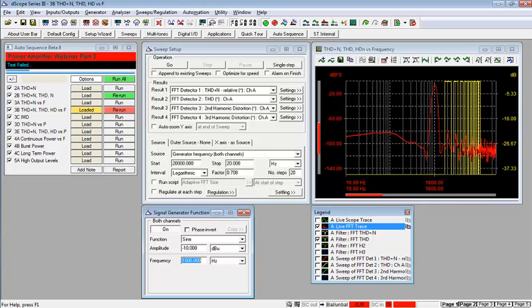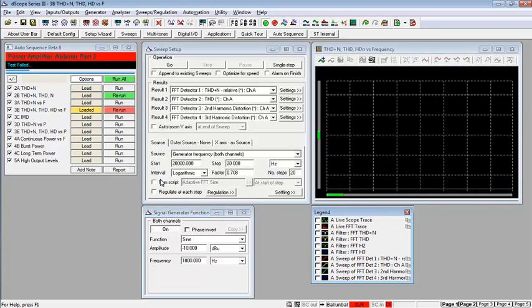What I want to do is to run a sweep that gives me the best of both worlds. I want to have a small FFT size at high frequency where I don't need the resolution but I would like the speed, but I want to use a large FFT size at low frequency where I have to in order to obtain the required resolution. So what I'm going to do is turn on this clever little script here, adaptive FFT size. This will fire on every sweep step and it will select the most appropriate FFT size to give me the best trade-off between measurement speed and resolution.